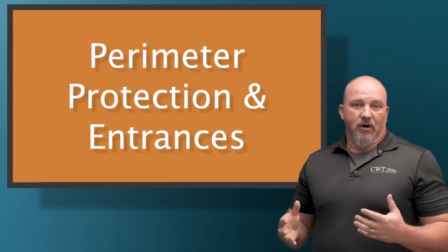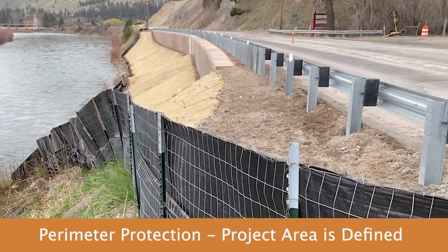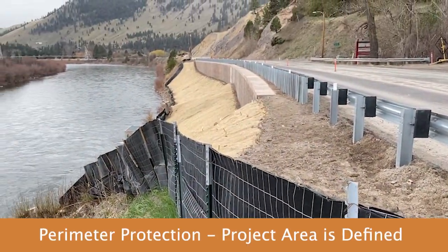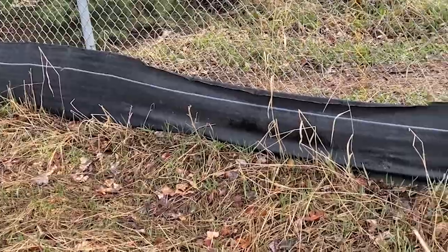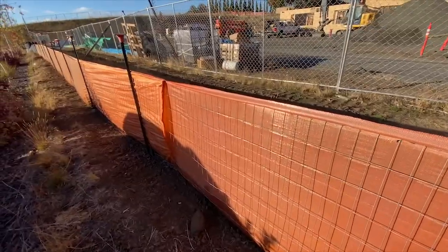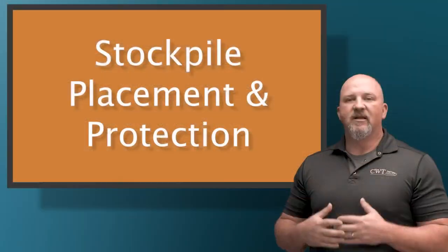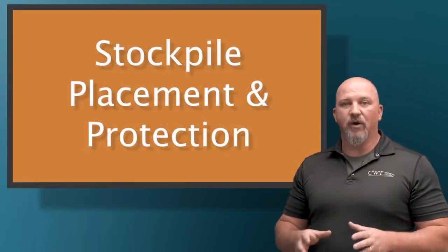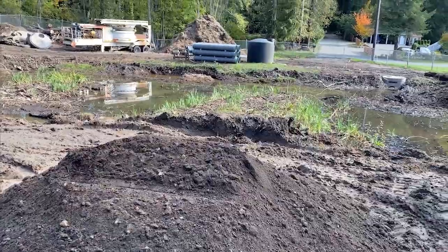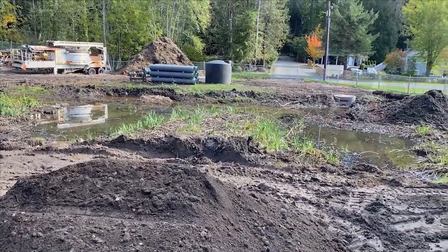We need to make sure that our project area is defined and that the perimeter of that area is defined as well, so we're not allowing water to run onto our project or dirty water to leave the site or sediment to leave the site. Stockpiles are a notorious challenge on projects as they are high-risk features that can cause erosion for us.